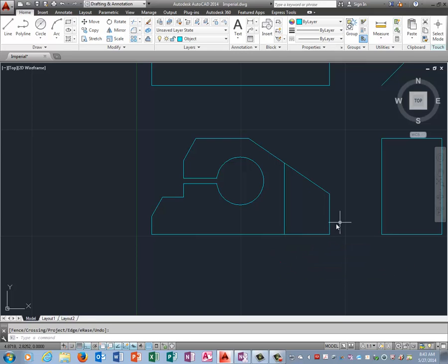And this is pretty much my front view. I got a little circle over here. This is pretty much all of the object lines in the front view minus this circle. So let's do that circle really quick. Offset. He's 0.5 from this line. And he's 0.44 up.